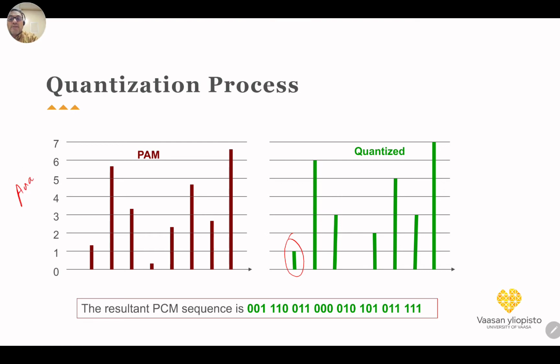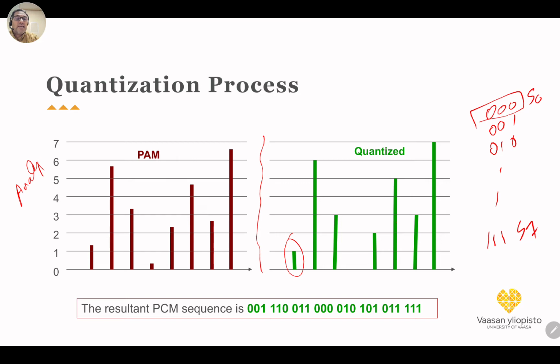So from the analog signal, we take sampling in time, quantization in level, and then conversion to PCM. Now we can assume, for example, that this is in 3 bits, so we have 000, 001, 010, until 111, and each one can be seen as a symbol of the output. For example, this could be S0 until S7, or it depends on the modulation type.